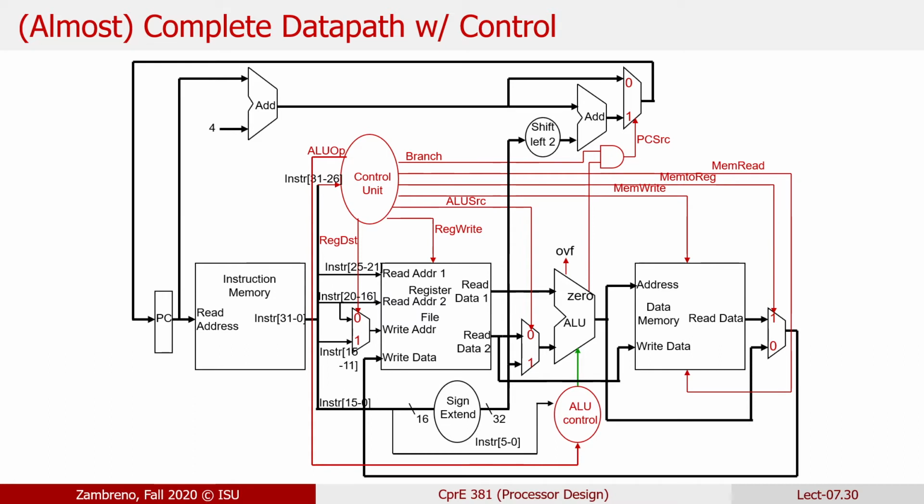David, you asked a good question here. That is something we're going to have to wrestle with a little bit. How do we reset the program counter? That really depends on a lot of other things happening in the system. So, from the perspective of our instruction memory, at least as implemented in our lab, we're going to be initializing that instruction memory exactly the same way you initialize the data memory for lab 4. We have a hex file, which will correspond to MIPS assembly instructions. There's a command in ModelSim to initialize that memory storage via that hex file. And from that perspective, it'll just start at address 0.